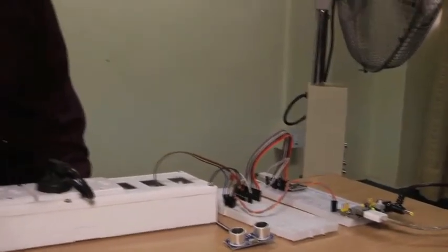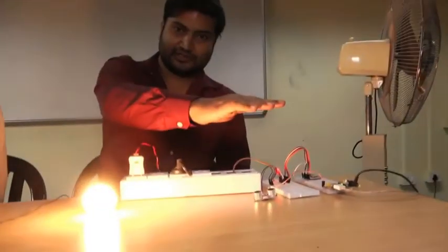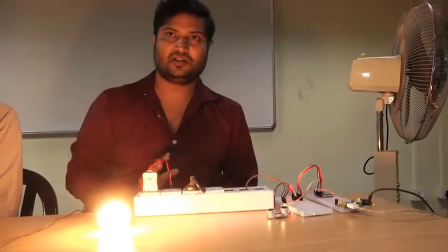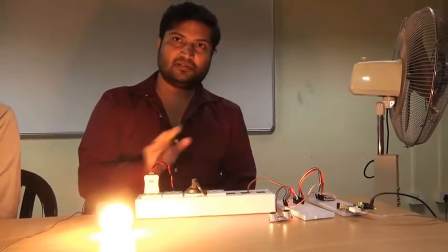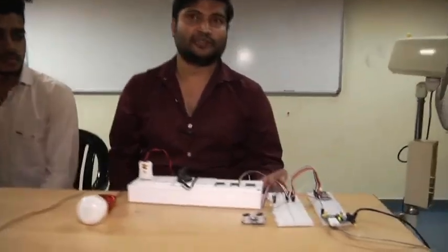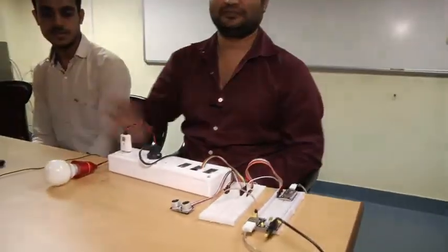Okay. Now we have the ultrasonic sensor. Through the ultrasonic sensor we have simulated motion detection. So when we go closer, between 5 cm to 50 cm, it will automatically turn on the bulb. So now I am going. See, now the distance is below 50 cm, that's why it turned on. Now once again if I go there, it will be turned off. See, now it is turned off. So whatever action is taken by the Node MCU server is sent to the ThingSpeak Cloud. So that data is here.